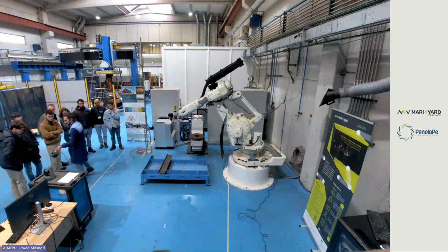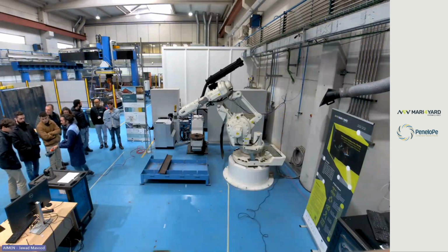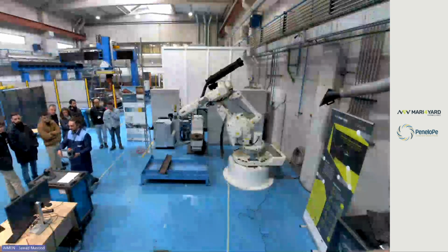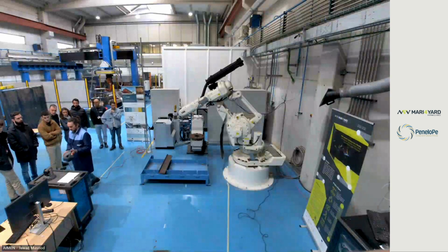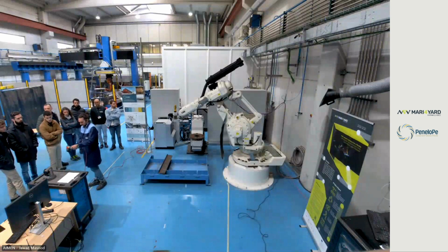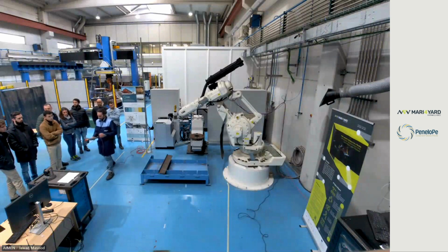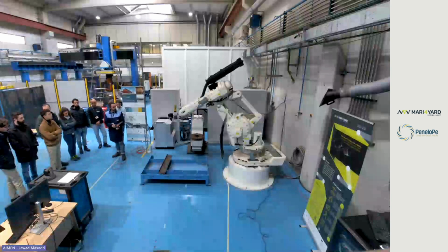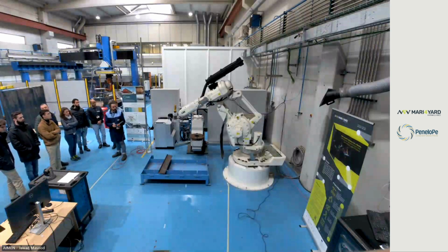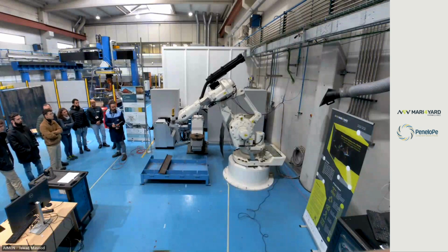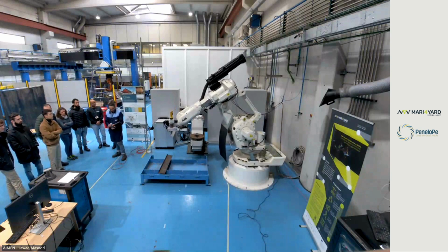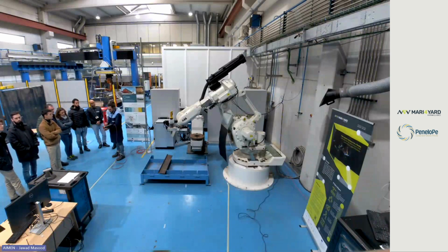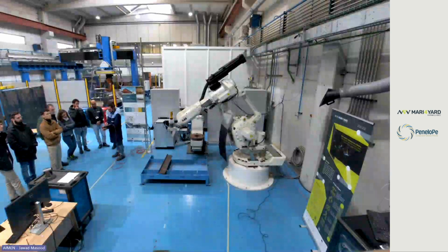So this is the second point of the square. I have to save it. Okay, modify. Now I move the robot to another point. For example, this point. This is a good point. I add again the third move L instruction with the name of square 30.